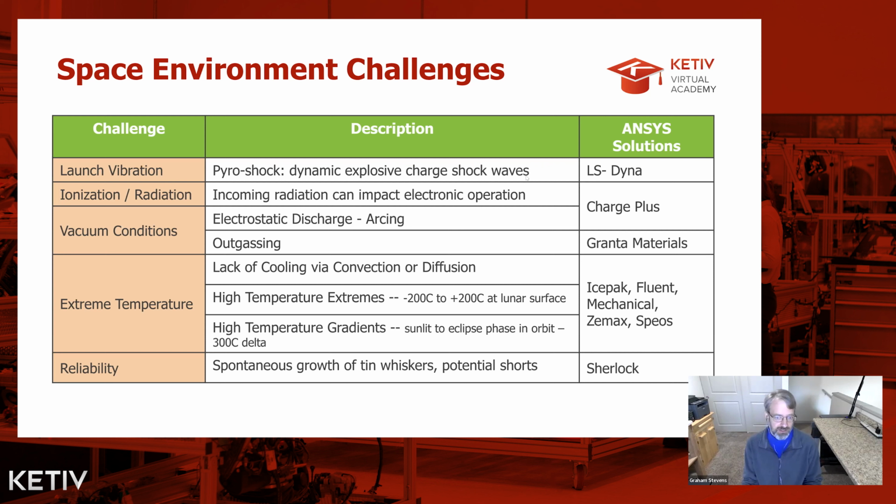So the first challenge is launch vibration. When we do a launch and my electronic box is on a rocket, there's basically a dynamic explosive charge that's lit underneath the rocket, and then obviously zooms forward, and there's a shock wave and associated sort of vibration dynamics, and so we need to make sure that our electronics will survive that, that the vibration isolation that I might have put in place works. And so to solve that challenge, you would use LS-DYNA or Ansys Mechanical.